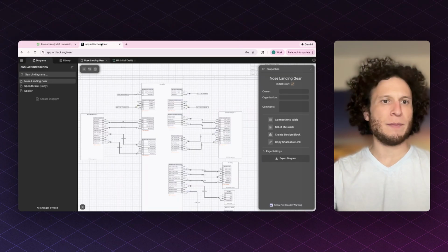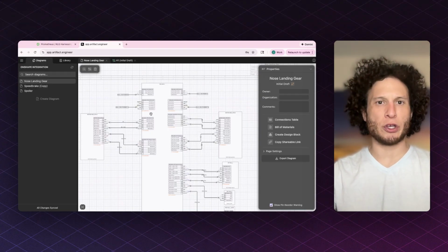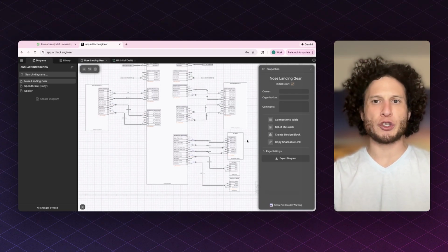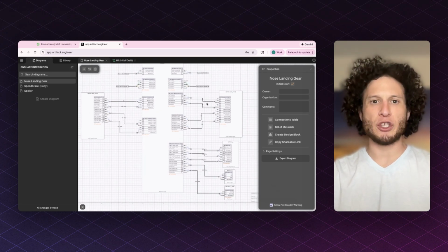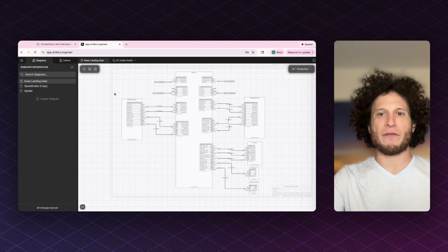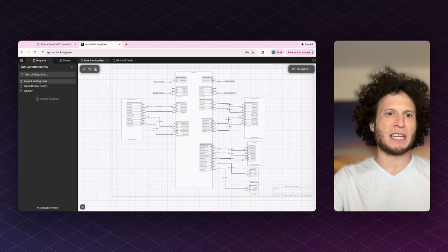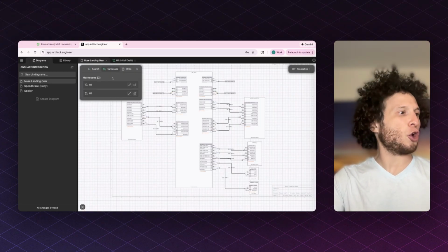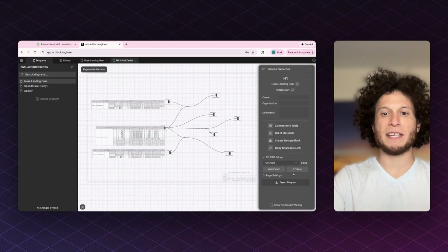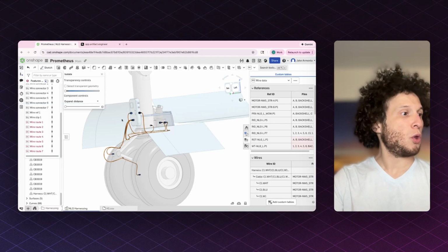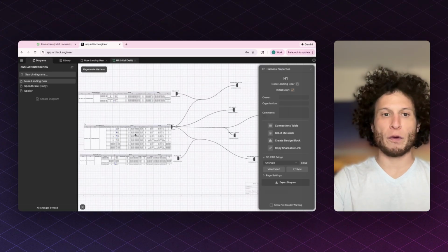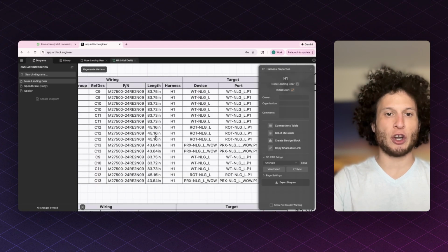Over in Artifact, if we look at the schematic, we have an I/O controller, 2 steering actuators, and a variety of sensors mounted to the strut and axle. We're going to call this harness H1, and we're going to bring it on over into Onshape. Now, every CAD package is different, but the overall process is essentially the same. After creating a schematic in Artifact, we create the harness, and then from the harness, we synchronize the schematic data with CAD. We route the harness in 3D, and then we synchronize the final data back over to Artifact to be captured in our build documentation.